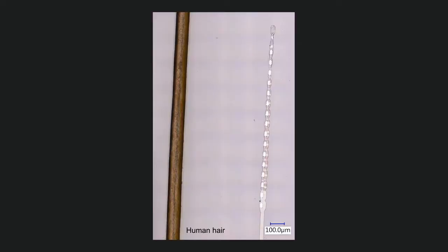So we built one out of microfabricated thin film polymers. Just like in semiconductor chip manufacturing, we use a layer-by-layer process that generally consists of 3 repeating steps. We're always either depositing material, patterning a material through photolithography, or etching away a material. Depending on the complexity of the design, these steps could be repeated over 100 times. And to make things more challenging, we are limited to materials that are safe for the body.